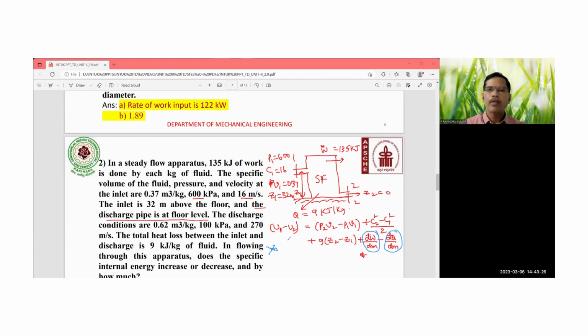So finally when you make the calculation, substitute the values of P2, V2, P1, V1, the numerical values over here. Next, the kinetic energy at the exit and the kinetic energy at the inlet section, divided by 1000, because all these things you have to make in kilojoules.